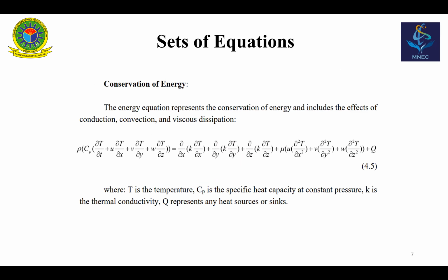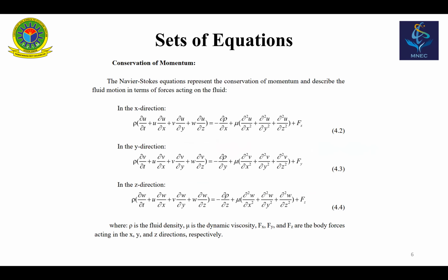equations more simplified. You can see that here, if we take the example of a turbulent flow, and if we take the momentum equation in the x direction, this equation depends on one of the variables, the density of the fluid, that is rho. If you consider that throughout the whole computational domain, throughout the time, the density of the fluid remains constant, then the equation becomes more simplified.